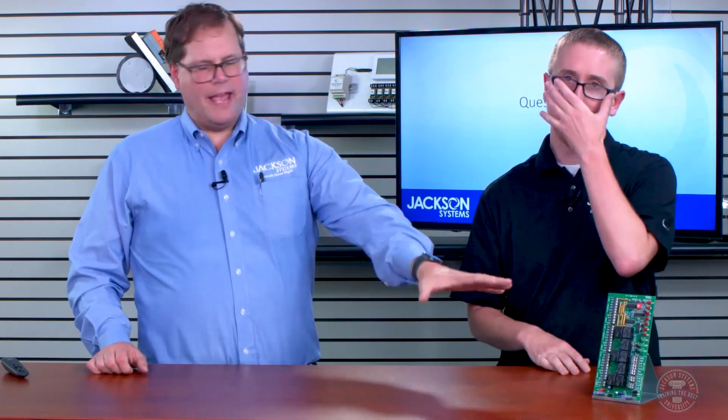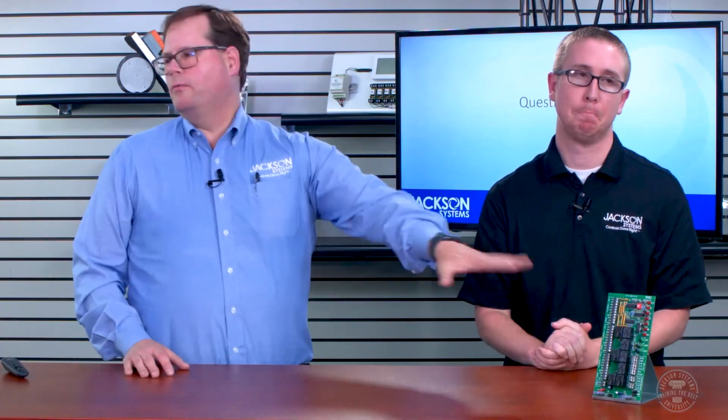If one thermostat thinks that it's below balance point and another one doesn't, it might not cause any real issues, but if you ever had to go back to the job and troubleshoot it, it would be unbelievably confusing. It's always best to let the panel do the balance point work for you, whether it's I/O or Honeywell, anybody's. Since it's really controlling the balance point, it's the device that really needs to get the outdoor temperature.